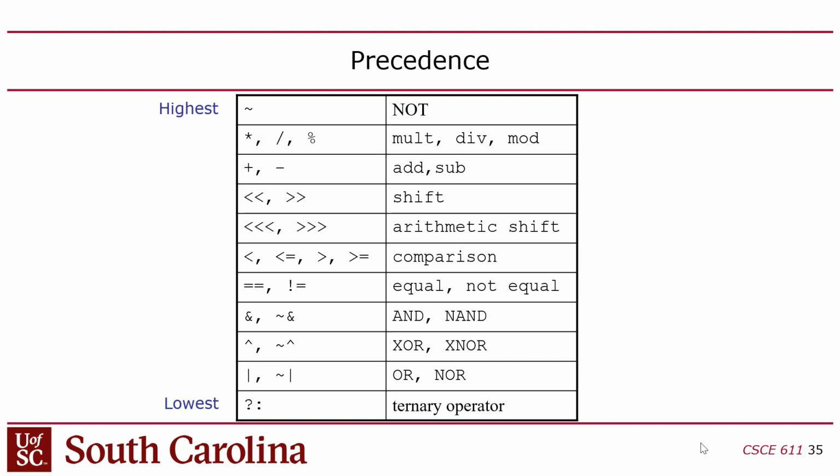So we have the not, which is the bitwise complement operation. Then we have mult, div, and mod. So these ones you generally are not going to ever use in Verilog code that you intend to synthesize, because whenever you're building code that has a multiplier, you're usually going to define that multiplier at a lower abstraction. You don't want to give the synthesizer the ability to generate its own multiplier architecture, because there's this huge design space for multipliers.